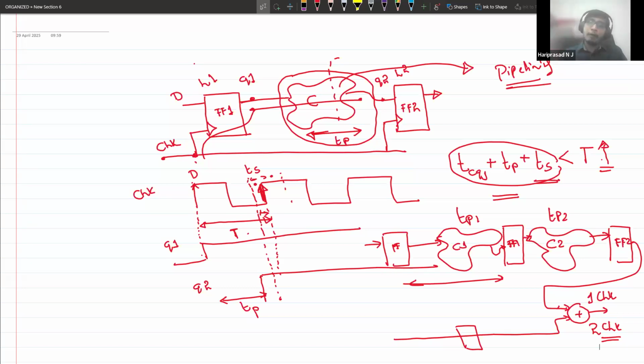So these kinds of constraints, false path and multi-cycle path, you have to put at the end of the design. Don't put them in the beginning of the design. Once you understand the whole design and see that these are known timing violation paths. When I say known timing violation path, it doesn't mean that there is a timing violation and you leave it.